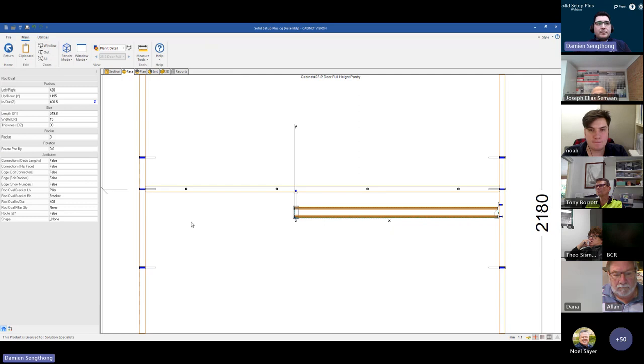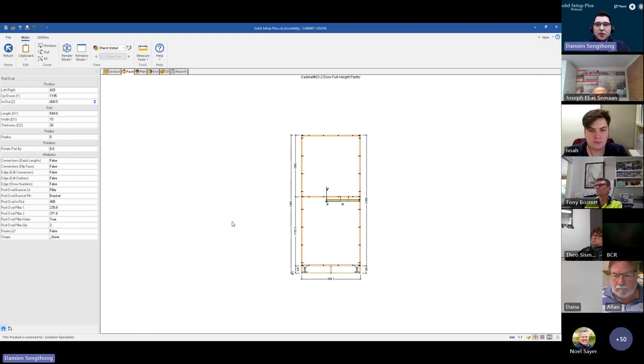If I select the oval again, you can also change the quantity of pillars that you require. So you have the option of 2 or none at all. If I apply 2 here, that will be in addition to your end bracket. Once you activate the sensor pillars, you do have offset options on the left-hand side, your 2 attributes for pillar 1 and pillar 2. So you can adjust these as required. So that's using the oval rods.